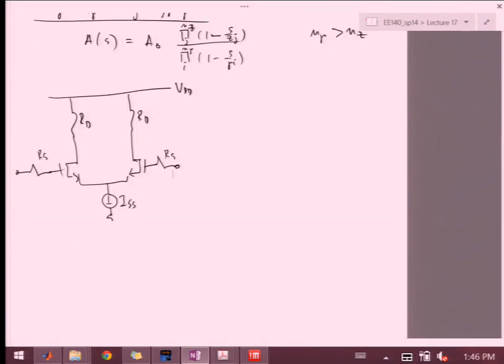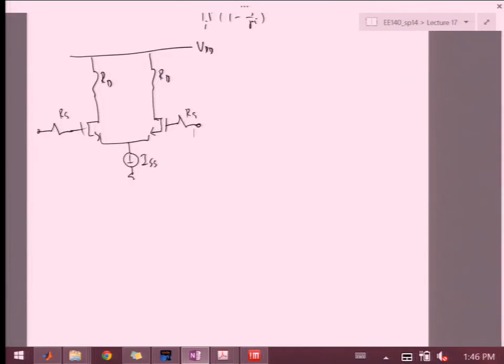This is the source resistance. Every source that I'm driving this circuit with will have some Thevenin resistance, right? And because I'm driving some capacitance at the gate, whatever's being seen at the gate, I need to take this into account, because that will be my first filter or frequency selective circuit that I will encounter, unless I'm driving it from an ideal voltage source, which doesn't exist in reality.